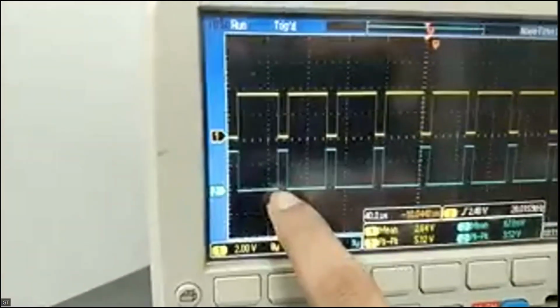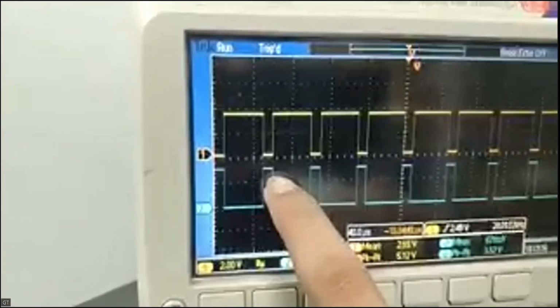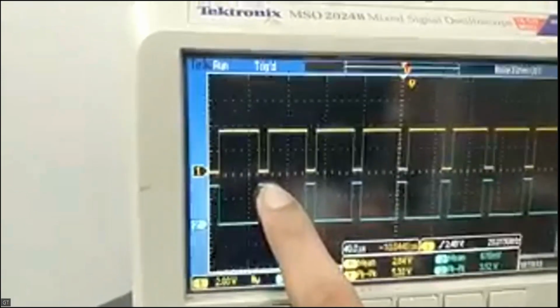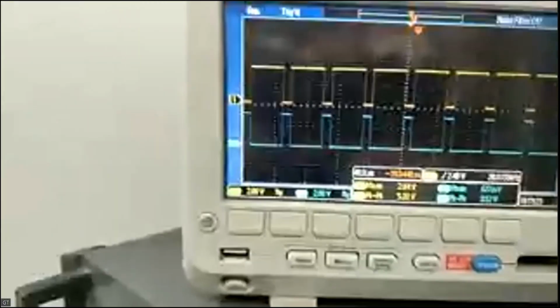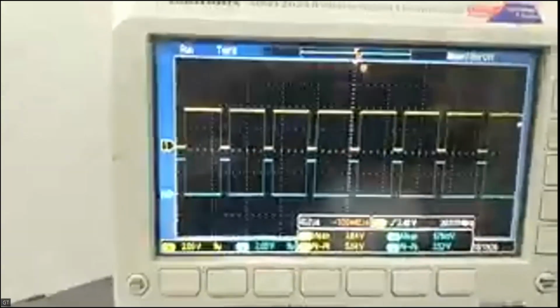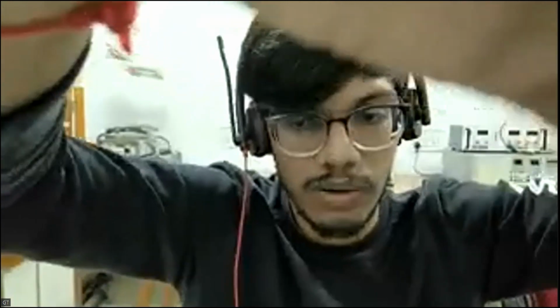It is 2 volts plus slightly more than 1, so it is more than 3, about 3.3. You can also put cursors there and we can see it will be 3.3. So the FPGA input it is taking is 3.3, and with respect to that input, it will give the voltages accordingly. Similarly, the FPGA that we have shown will also give 3.3. 3.3 is the standard voltage that is followed everywhere.